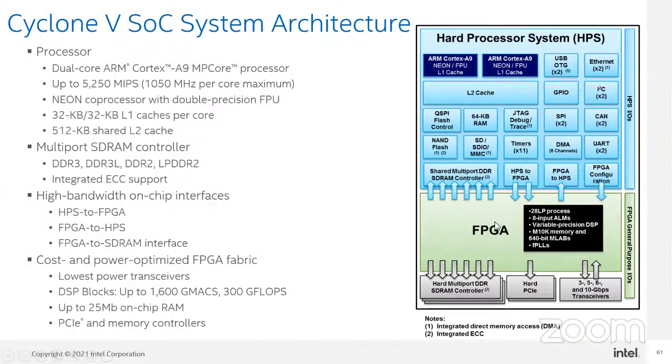And on the FPGA side, as I mentioned on the first day, you have an 8-input adaptive logic module. That is your factorable lookup table. And you have variable precision DSP that is available, which is a multiplier. You have M10K memory. One small difference is, if it is a Max 10 device, you have M9K, whereas when it is a Cyclone 5 device, each memory block will be 10K.